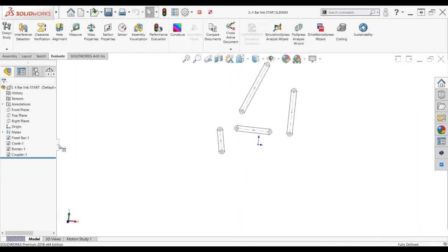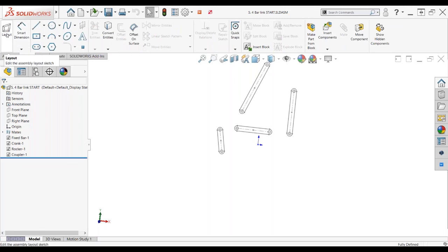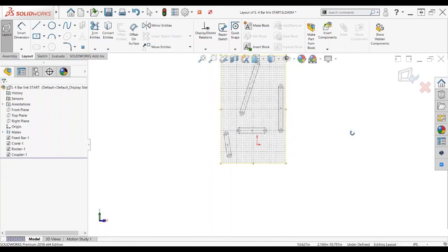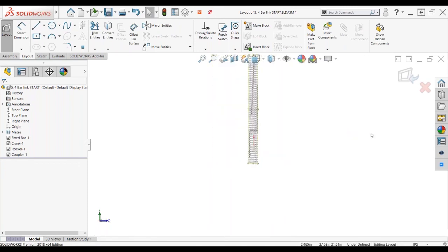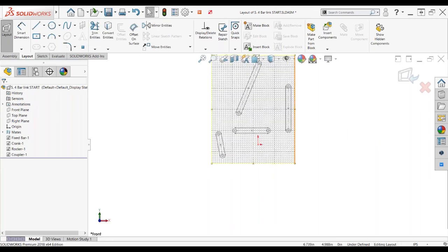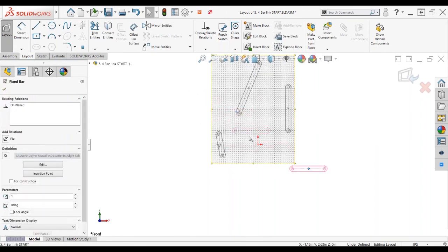Sketch blocks have another unique feature, and that's inside of the assembly environment. When I'm working with sketch blocks in the assembly environment, I can use them to test two-dimensional kinematic motion and get a nice little proof of concept. So in the layout mode of my assembly environment, I have put a whole bunch of sketch blocks. These sketch blocks are stuck on this plane. They're two-dimensional, they can't come off the plane, but they have all of their translational and rotational degrees of freedom upon this plane.